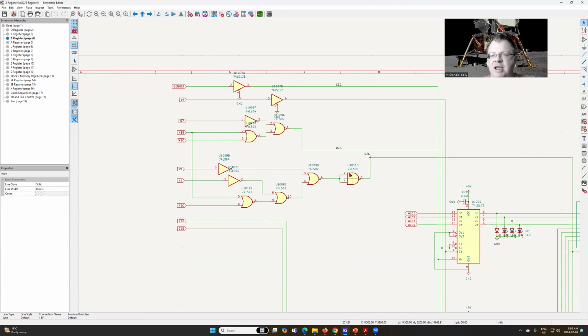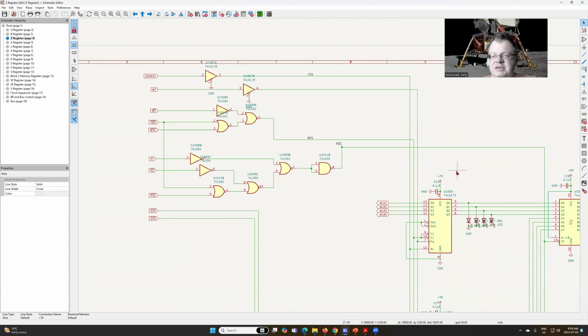And because I had an extra NAND gate floating around, I just tied the two pins together so that we can save chips. You can see here, and I'll show a little bit down, I used 6 inverters already, and there's 6 inverters on each chip. Rather than adding one additional chip just for the one inverter, I thought I'd use some leftover gates to do that. So that, in essence, takes care of loading data into the bus and loading data out of the bus.